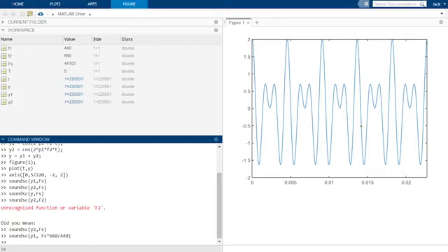In fact, Y1 becomes a 660 Hz cosine when we adjust the sampling rate. The only difference now between the two sounds is that Y1 is shorter in duration. When played at a faster rate, the sound finishes more quickly. Instead of 5 seconds, it is now 3.33 seconds.